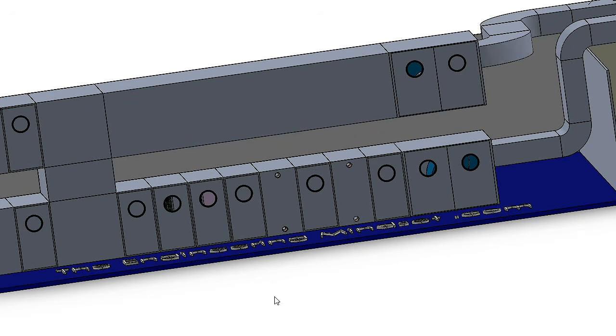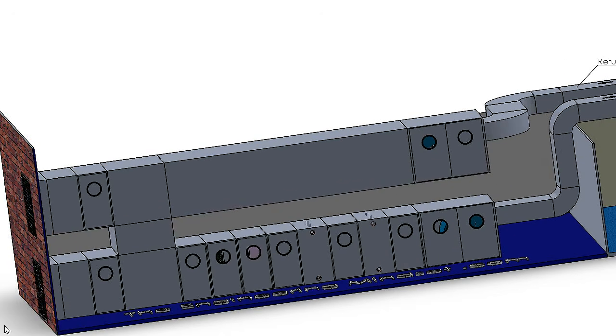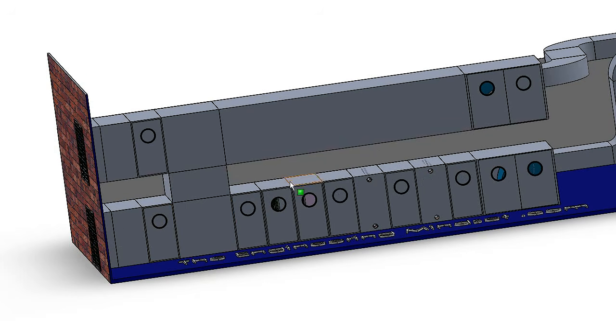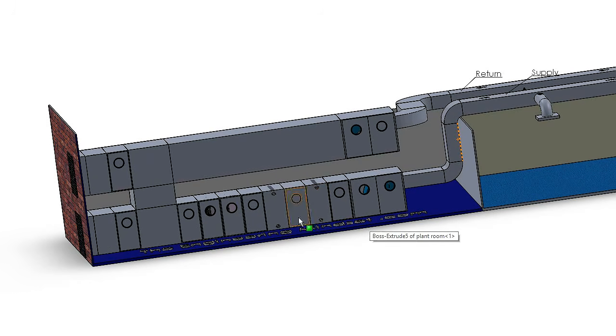So let's go back to the AHU. Position that a bit better. So the supply air will enter into here. It's being sucked in, and there's a fan in here, and we're going to look at all these components one by one, don't worry. We'll just go through and make sure you understand what the system is doing first. So once that air has been pulled into the AHU, it passes through here, which is the HVAC parts inside, and that then gets pushed into the ductwork, and that gets sent off around the building.